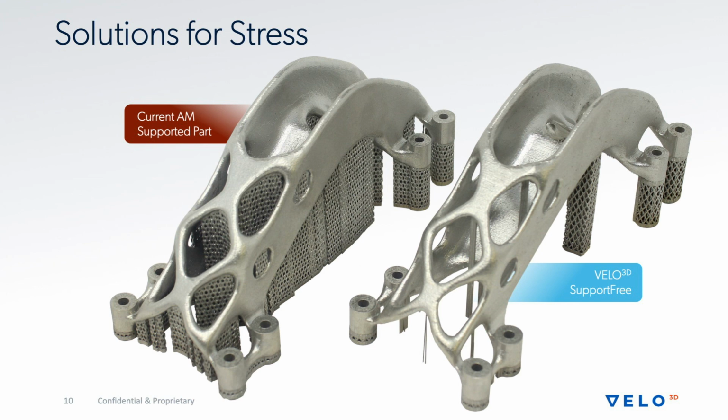They cost time up front for engineering, they cost time to print and material to print, and most significantly probably is that they introduce a lot of post-processing problems. Right? I think anyone familiar with any kind of 3D printing is aware how much time and money and energy can be spent on removing these supports, and then having to finish the surfaces that were supported, because you're left with a degraded surface finish wherever anything was supported.